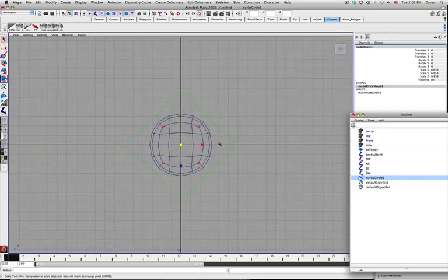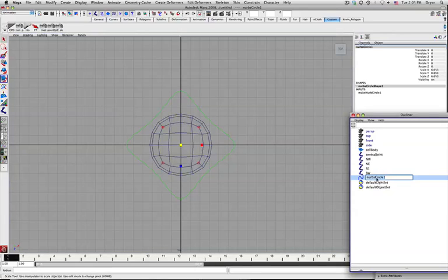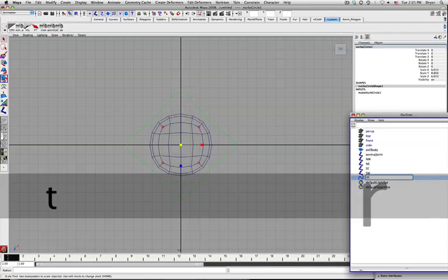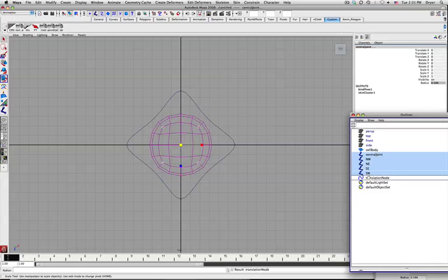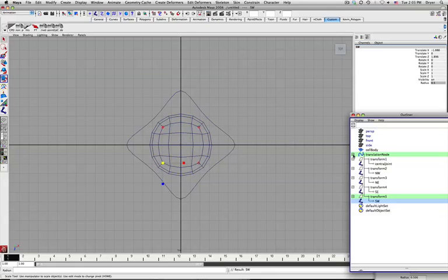So now I'm going to parent all of my joints to this. I'll just call this translation node. And this is the object we can use just to move our cell to any point in the scene. Just for convenience sake, sometimes called the God node too. So select all these and just middle mouse drag them on here. If I open up, you can see that my joints have been parented to my translation node here.